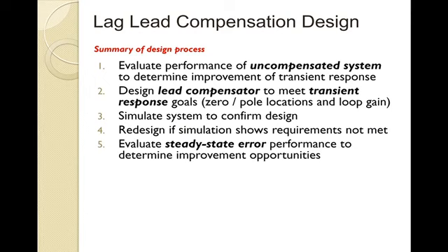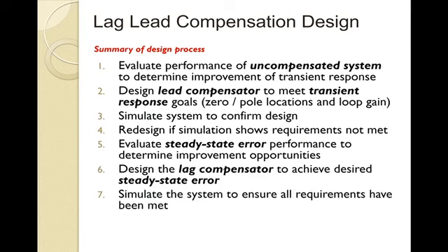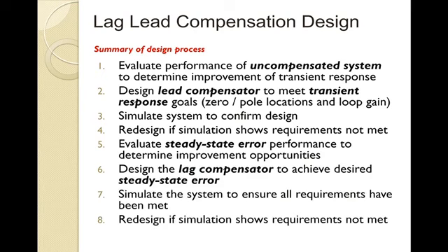evaluate the steady state error performance to determine any improvement opportunities. Again, design your lag compensator to achieve that steady state error, simulate the system, and then do a redesign if simulation isn't exactly showing you the results that you desire.